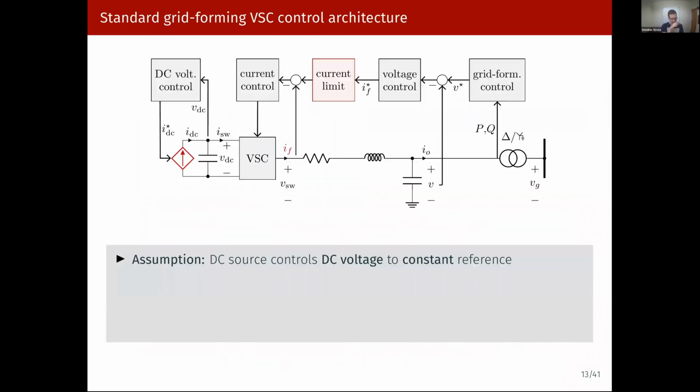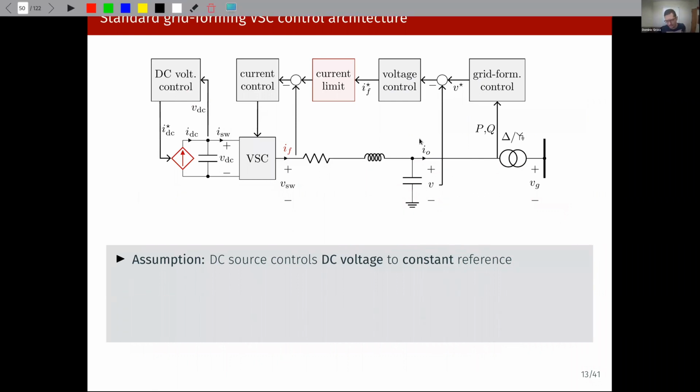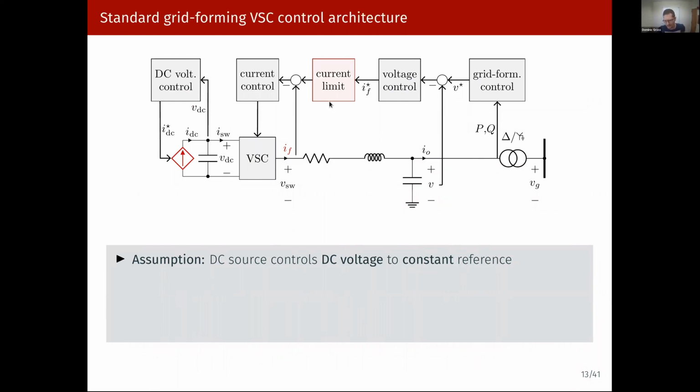Before I go on, let me maybe just briefly point out where that control actually factors in. So here is kind of an expanded view of the power converter. You see a typical 2-level voltage source converter setup where you have a DC voltage, some DC source, and then the DC voltage is modulated into an AC voltage. There's an RLC filter here to remove switching harmonics.